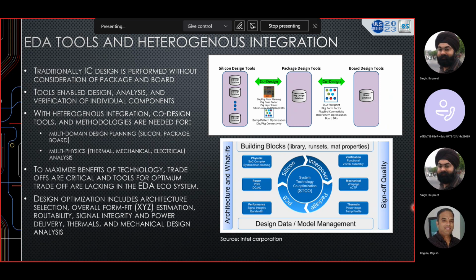And routability, routing estimations, right? Initial part of the design, do you have the complete routing? No, right? It's not realistic, but you probably need to go with some estimations. But can those estimations be too off? Then it's not going to help us, right? So the tool flows have to estimate based on whatever technology information we're able to provide. Maybe when we're designing monolithic chips, we already have that type of infrastructure today, right? But we have to build that infrastructure to scale up to the chiplet ecosystems.